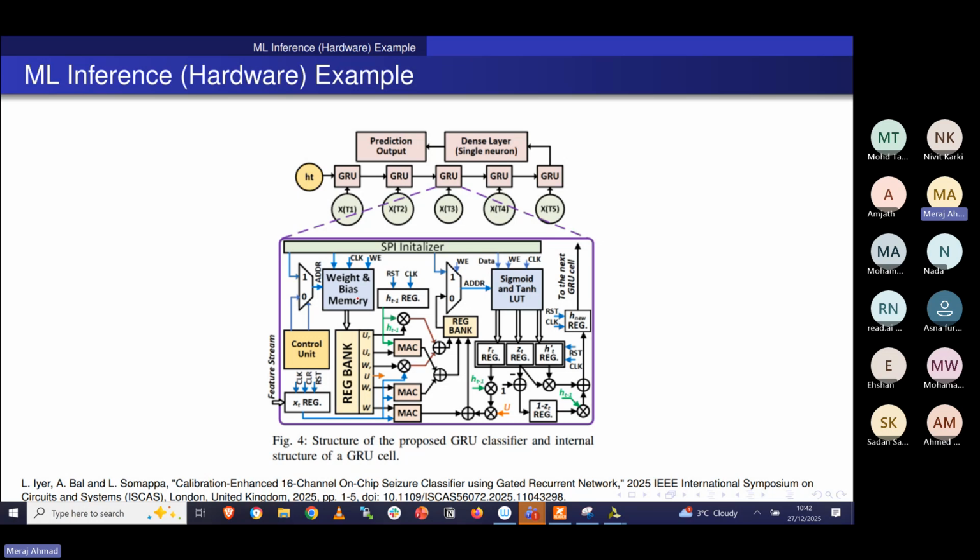If you see the mux, one thing we didn't cover was memory. We had all registers, but sometimes you require very large storage, like hundreds of kilobytes. It's not area efficient to store that in registers. So for that, you will have a memory block, which you can instantiate in your data path.